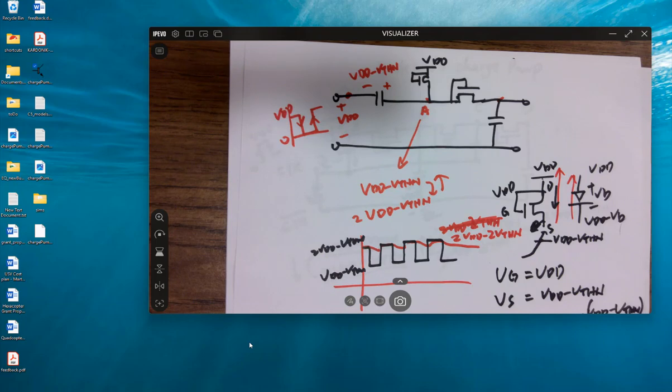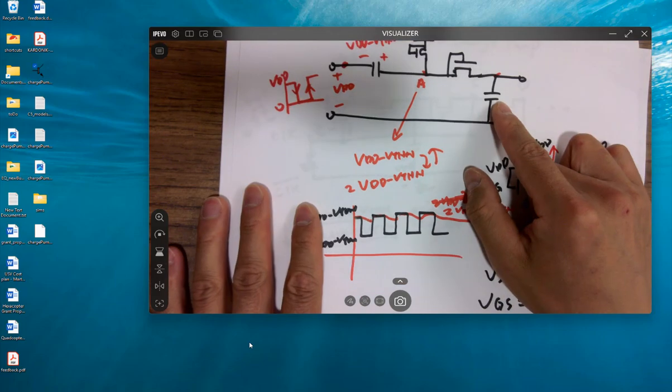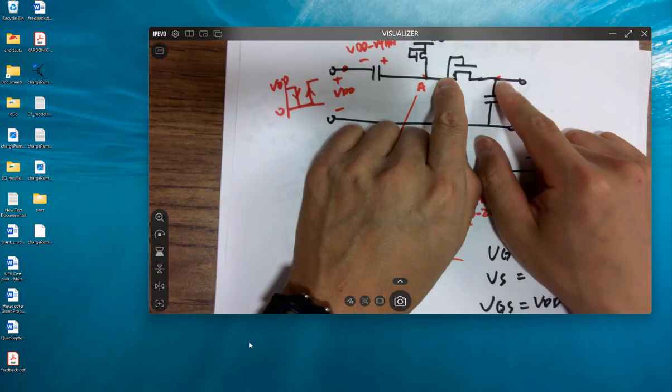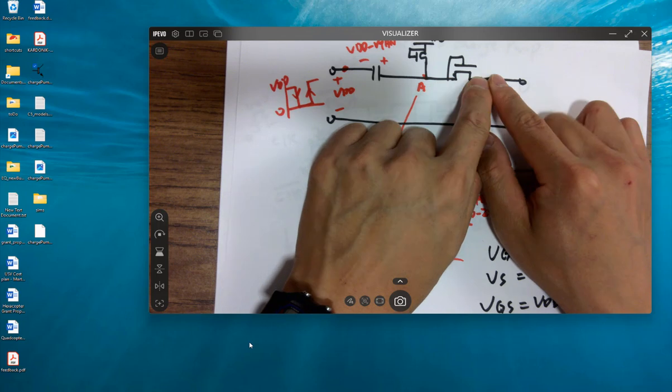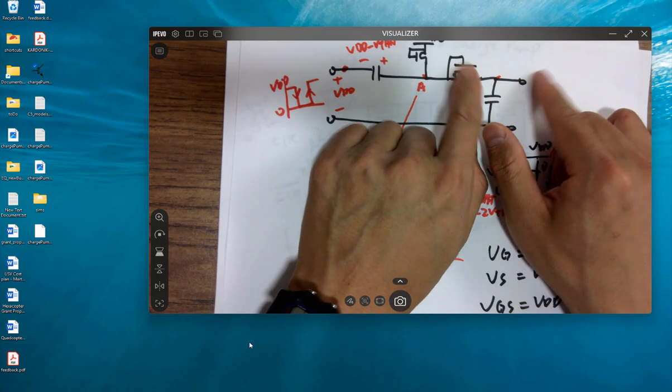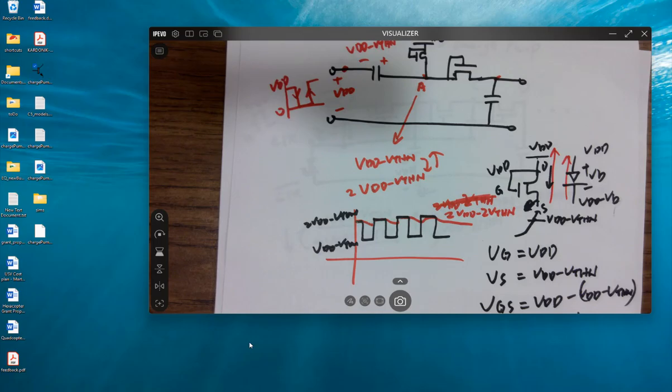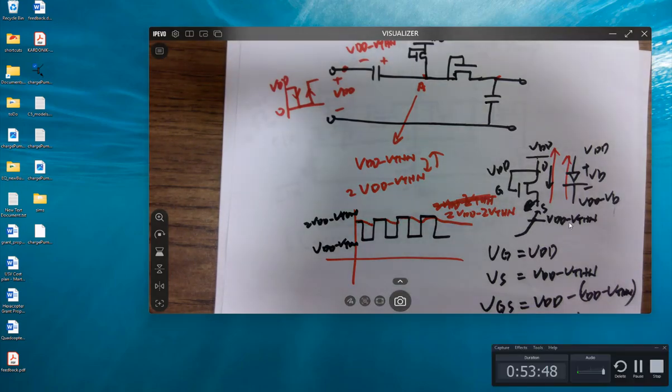Okay, so it shouldn't really oscillate enough to have... Depending on application, right? For digital circuits, you don't want it to oscillate. But for charge pumps and low pass filters, that's the whole point. We want a big capacitor to not fully charge and discharge, so it gets smoothed out. Okay. If it's used as a filter, then you don't want to fully charge and discharge. For digital circuits, you're trying to drive it efficiently, so you want to charge and discharge fully. Okay.